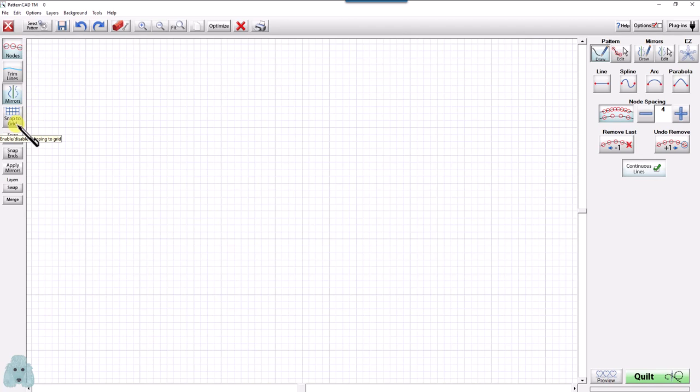That way it'll be really easy to draw straight lines because my line will continue along one of the lines in the grid. I'm going to select Draw and Straight Line, and my node spacing I'm going to turn off. I want to create a continuous line pattern, but I don't want to have all the nodes being placed there. I'm also going to have continuous line pattern checked, so it's just like a drawing that I'm creating.